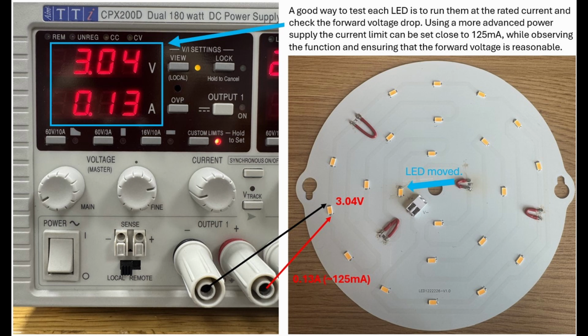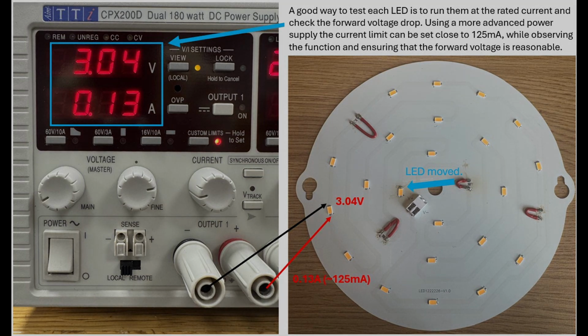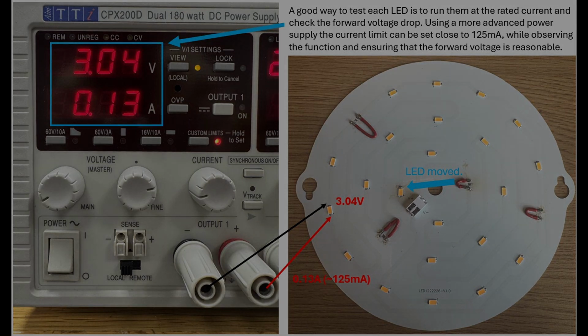Another way would be to replace the LEDs completely, but then I need to find the make and model of these LEDs and replace all of them. Here I just needed to move one of the LEDs, which was quite easy using a powerful soldering iron to heat up the heatsink on the back and then just lift it off.